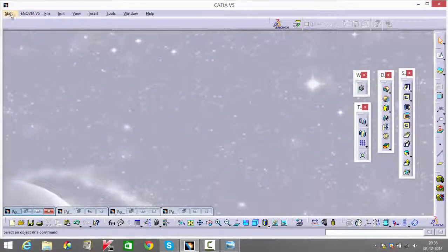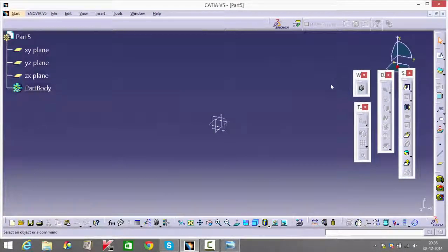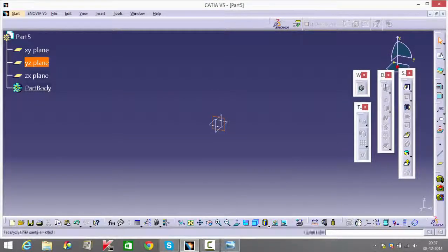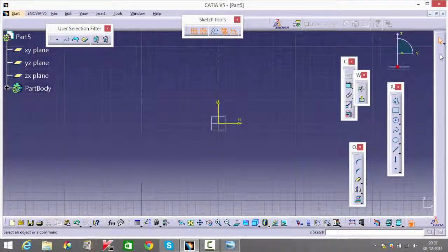Now one thing while doing the next part is it would require a little work, but if you really want it to look like how it's supposed to look, the small work that you're going to do right now is going to be very helpful anyways. So what I'm going to first start doing, I'm doing part 5 by the way, the bolt over here, and to get this kind of shaved off edge, I'm not going to be using the edge fillet option. Instead of that, I'm gonna be making a profile and then using the groove option. I'm gonna make that kind of cut off edges.